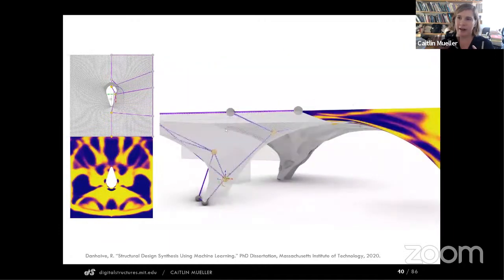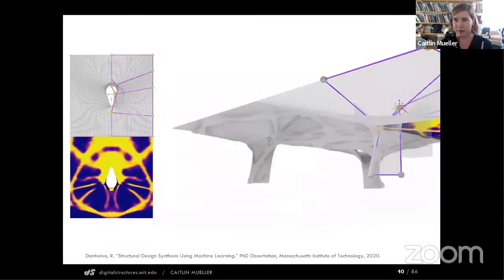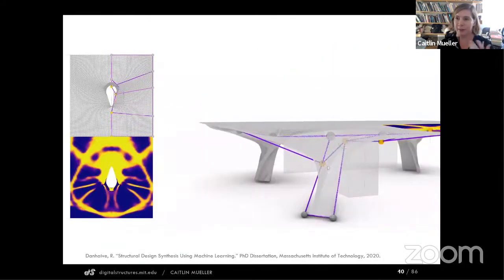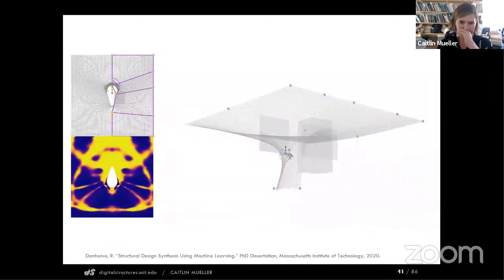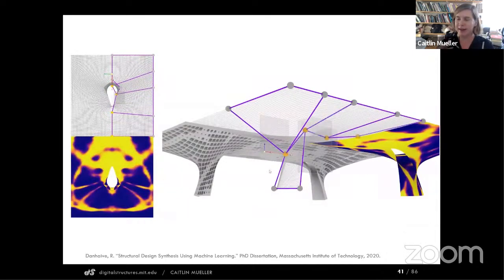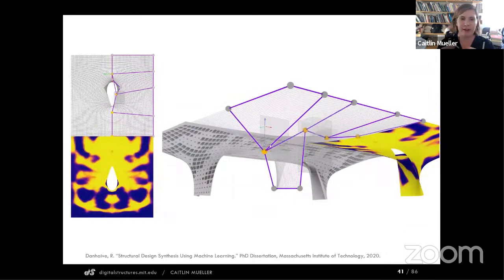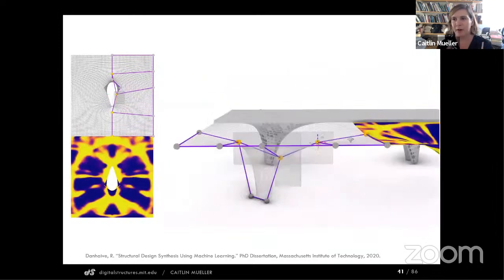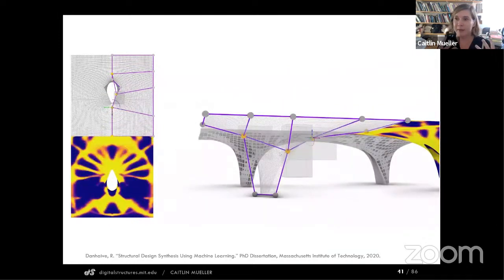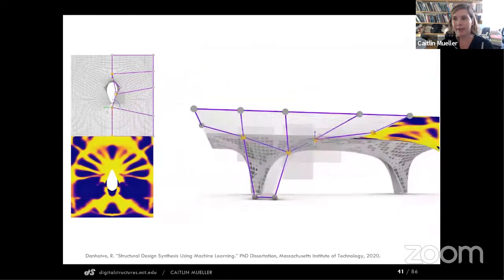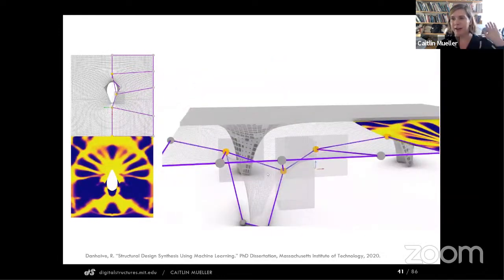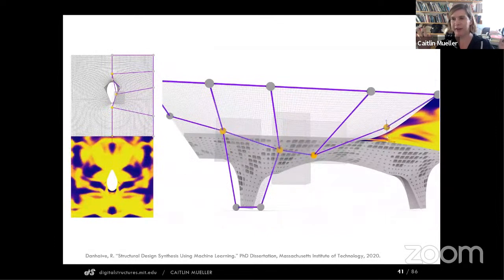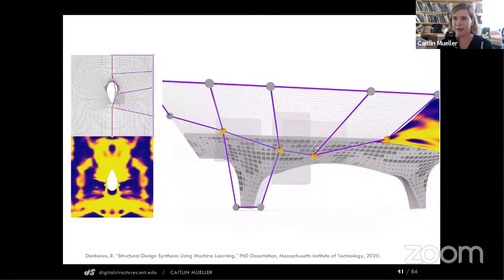Here, we're projecting that topology optimization information into an actual 3D model, so we can start to see what this would really look like if we were to build it and understand its implications. We can similarly use this information in a more abstracted way where we take the topology optimization result and use it to size elements in a waffle slab-like structure in order to, again, get this sort of real-time information where we've significantly compressed the traditional process of conceptual abstract design and final materialization. Now it's all in this one instantaneous feedback system.